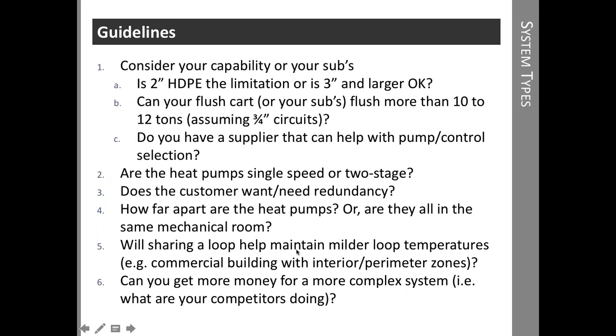Will sharing that loop help maintain a milder loop temperature? In most residential applications, it doesn't make a lot of difference whether you have a single loop for each heat pump or you have multiple heat pumps on the same loop. Now, in a commercial building, that's completely different. In a lot of cases, you can have heat pumps in heating and cooling at the same time, and so you're just sharing heat around the building, and that does make a difference, but it's rare on a residential application that you would have heat pumps in heating and cooling at the same time.